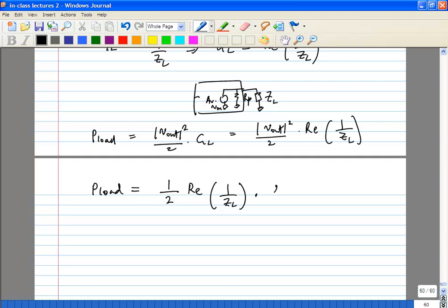What do you know about Vn? Actually, let's leave it in terms of GM. What did we calculate? GM times? Okay. V out is now GM times RP parallel ZL times Vn squared, right? Okay, and so your GT is this over half Vs squared over Rs, right?